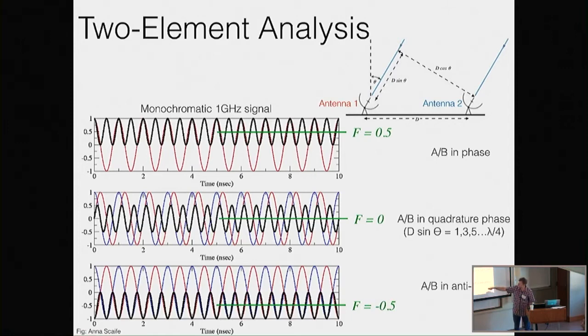If they're precisely out of phase, you'll measure an average voltage that's negative, because whenever one of them is positive, the other is always negative, and this product ends up always being negative. Inconveniently, it's possible for them to be out of phase by 90 degrees, in which case you're going to have an imaginary voltage of Jonathan's dreams. But you see that this product doesn't capture this information. The average here is 0, and so your correlator will spit out nothing.